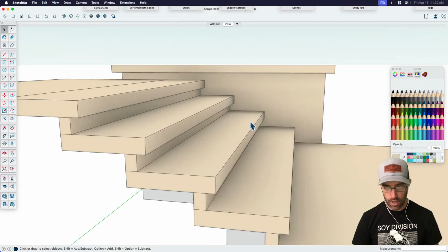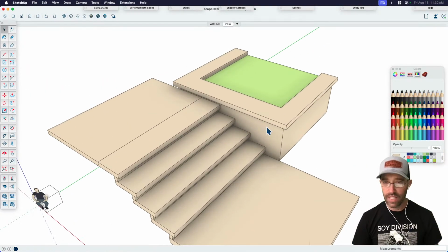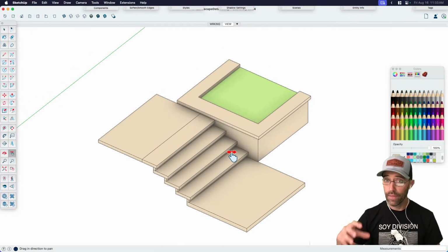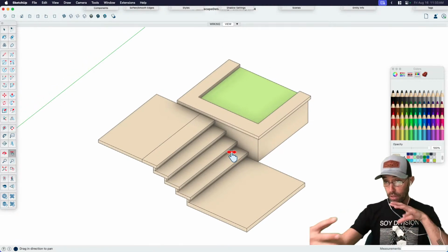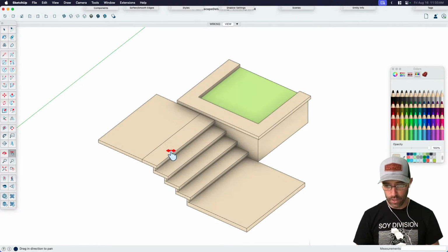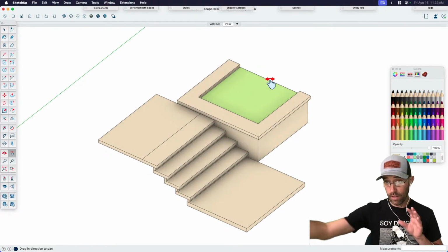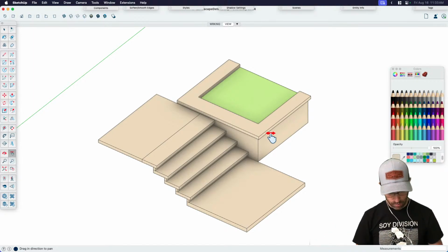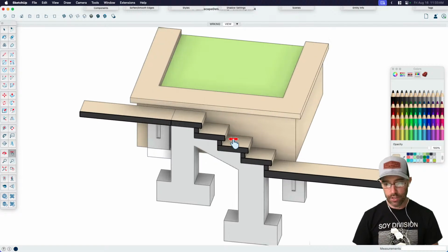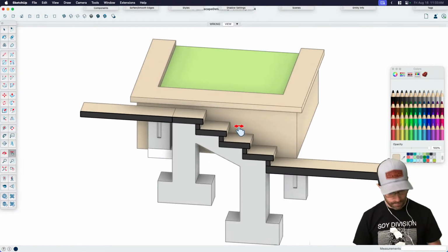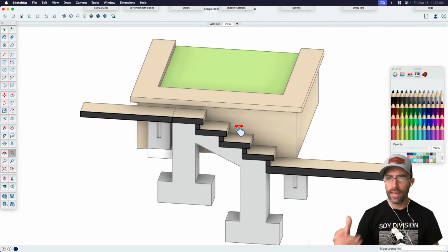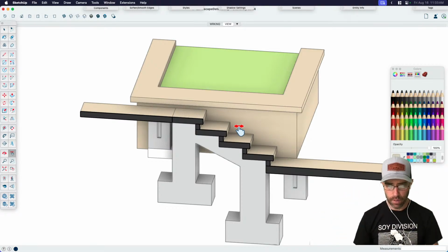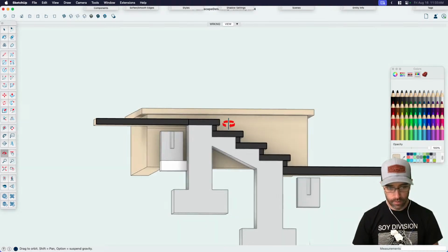Yeah. So if I toggle that section cut off, if I wanted to see it as an aerial view like this, let's say, for example, I switched my camera to ortho, and I wanted to show the relationship. Obviously I didn't finish the stair and I didn't finish the planter because the widths will vary, but this is a typical condition. But then when I want to show what's going on below grade, I'm using a keyboard shortcut, Shift S, and then what I can see is I'm now cutting away and almost revealing what's happening below. It's kind of cool. Very nice.